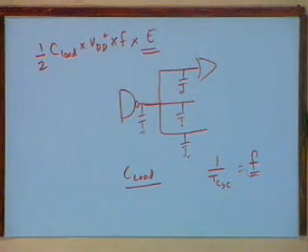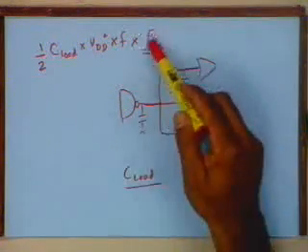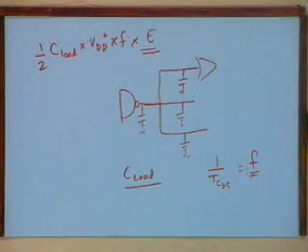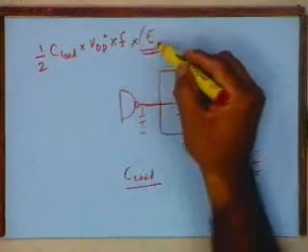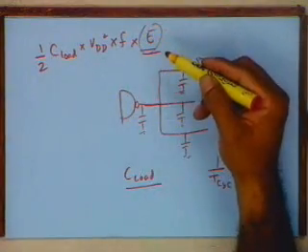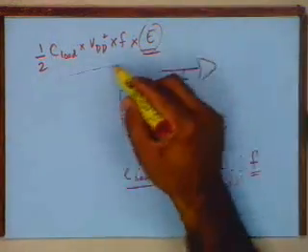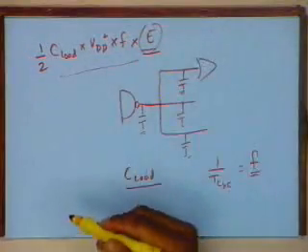So for example, in a particular clock cycle, if you expect a transition to occur, that is the expectation, a value between 0 and 1, and that gives you the total power consumption. If the expectation is that there are very few clock cycles in which a transition occurs, then the power consumption will be lower, otherwise it will be high.